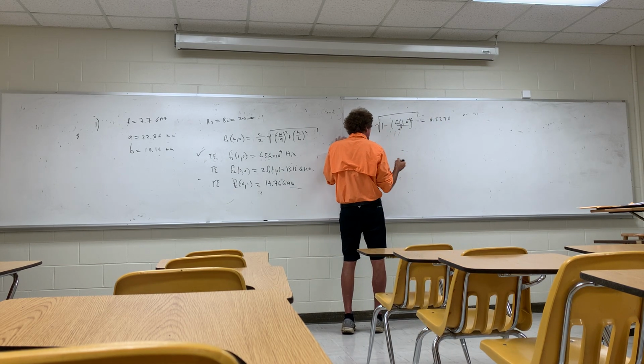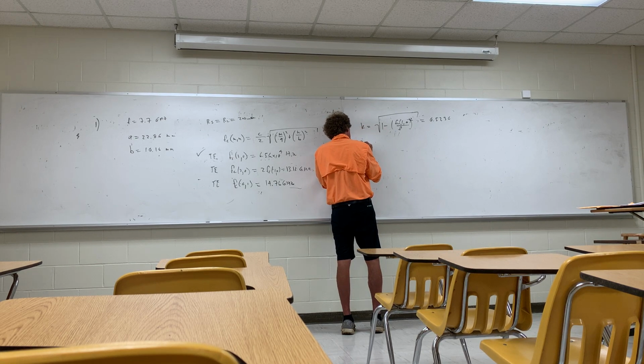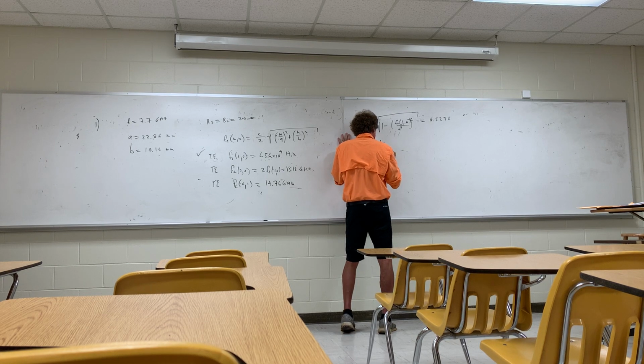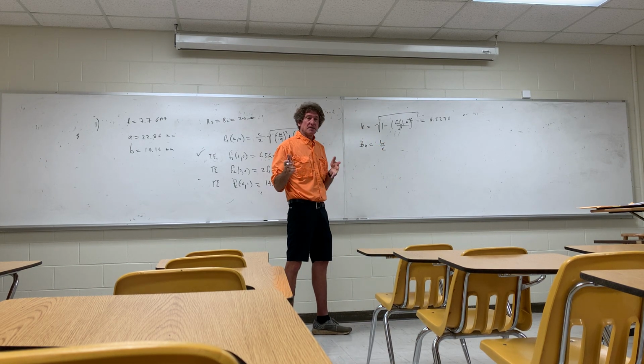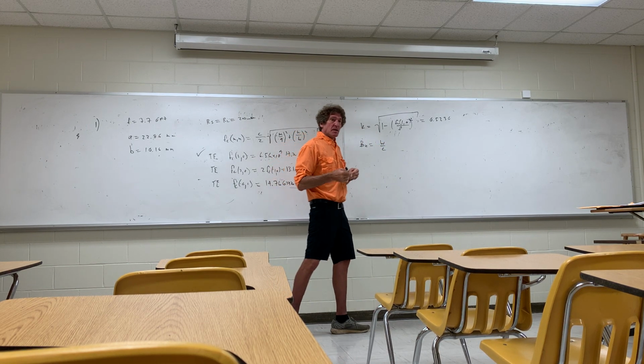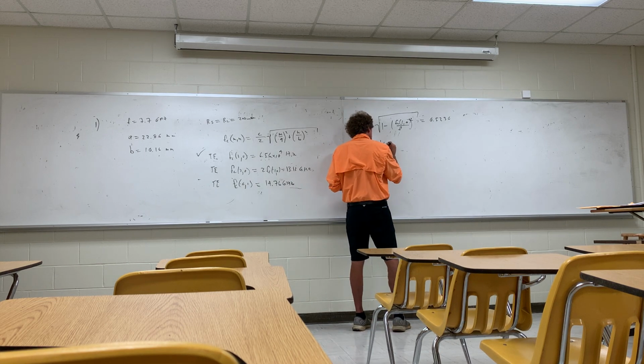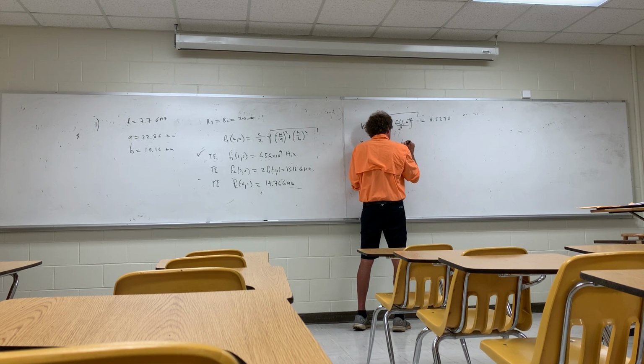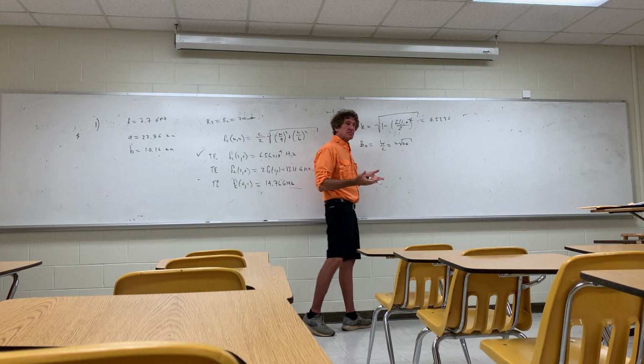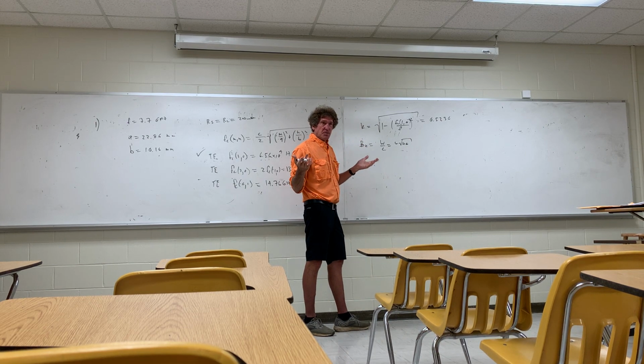So after that, then I'm going to get beta unguided, and that's just going to be omega over C. Y'all follow me? Because the waveguide is filled with air. So it would normally be omega times square root of mu epsilon, because mu and epsilon are both free space, mu naught epsilon naught.